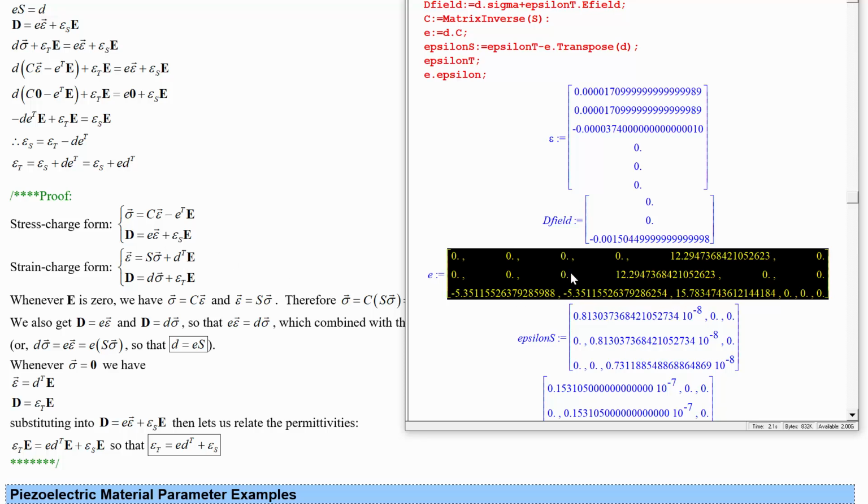You can get charge displacement in X and Y in PZT, but to do it, you've got to put the crystal into some shear strain somehow. So that's what's going on in these two components. You've got to put it into shear XZ or shear YZ in order to get that to happen.